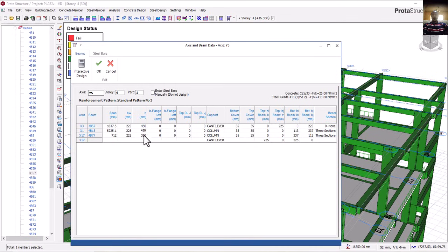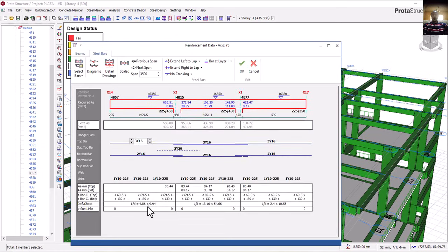So that the 450 will start coming from inside, not from the column. I'll come here. Okay, 4 against 9, which is okay. So this one is perfectly okay. Guys, if we subtract it, we still have 5 difference, which is perfectly okay. Can you see now? This is how you go about your interactive design. All that we have checked, all of the values here are more than 100. Also, if you look at this one, none is less than 20, and none of their deflections is less than 5. I can now click on OK.